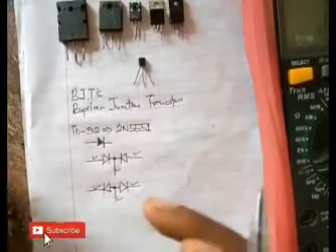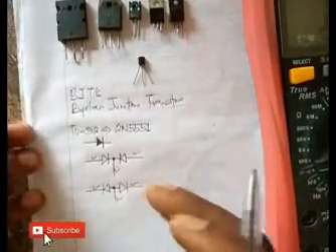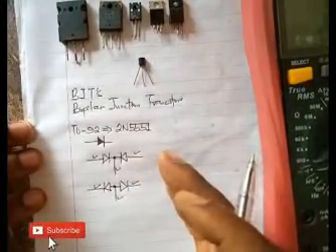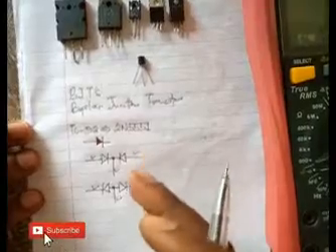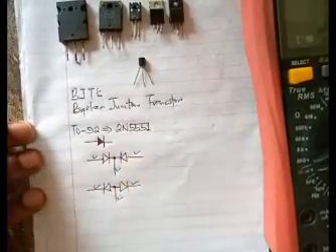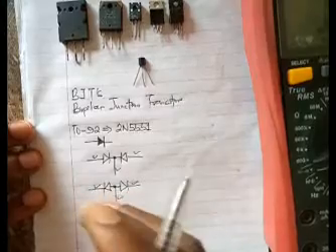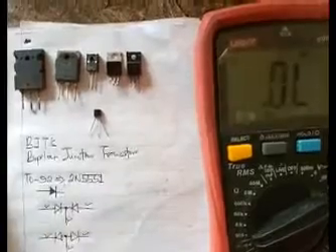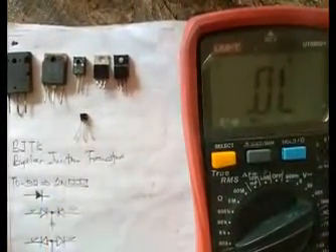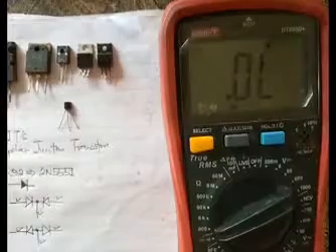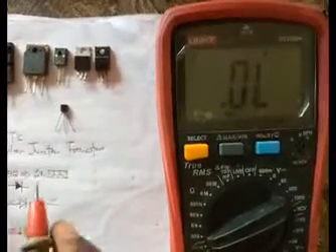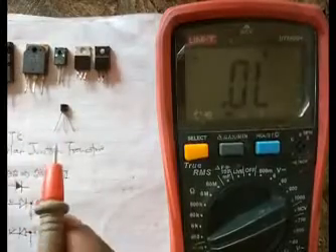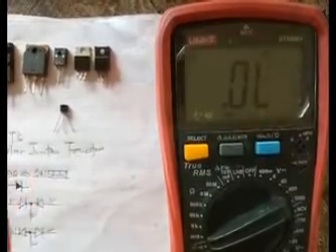All right, if you have that at the back of your mind, it helps you to test with an understanding of what you are doing. That is why we put our multimeter to diode measurement whenever we want to test a transistor. So let's quickly run a test on this 2N5551 and let's see if this transistor is fine. Now, the first thing you need to know about any transistor is that when it is not switched on, I'm going to mention the fact that transistors are used as switches.